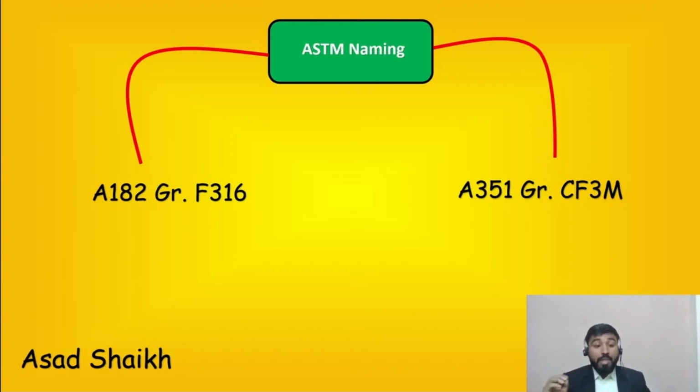So vendors, be very cautious. If the vendor gives you the UNS numbering system of the material, you don't know whether it is going to be a cast grade or a forged grade. And I'm talking about world renowned companies that could reject by saying that no, they want the forged grade and that is what is specified in their specification. So be very cautious of this point as well, and that is the reason why I put this here.